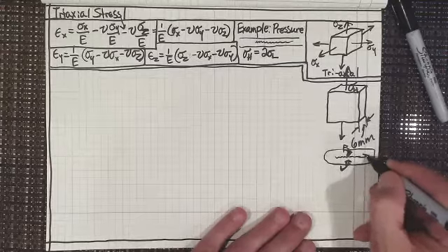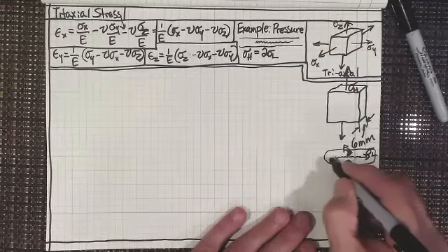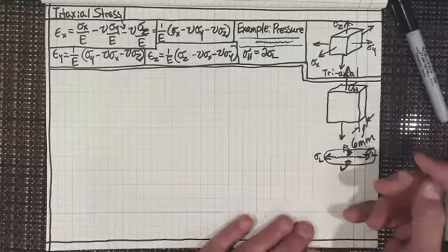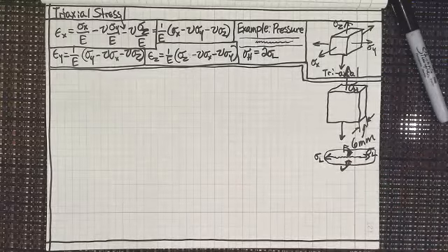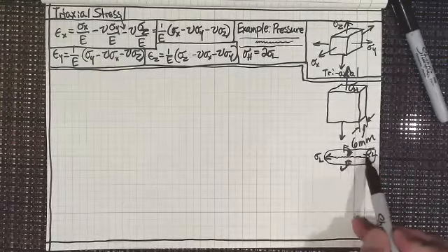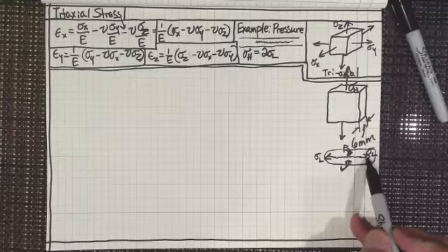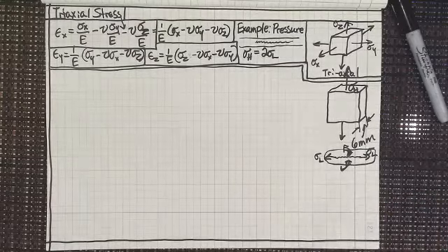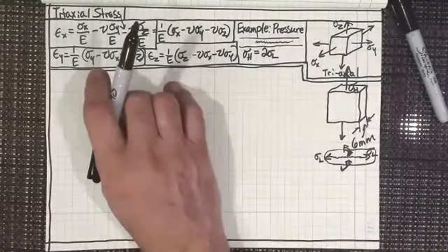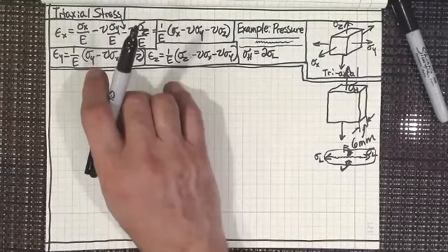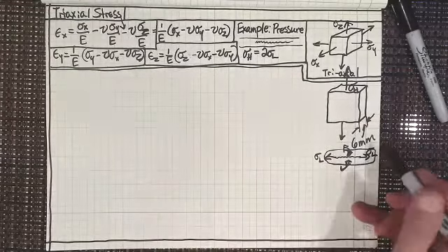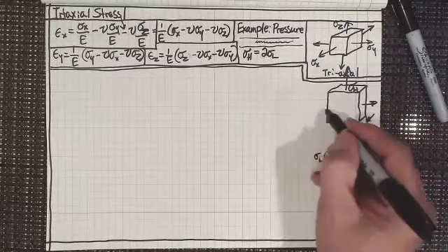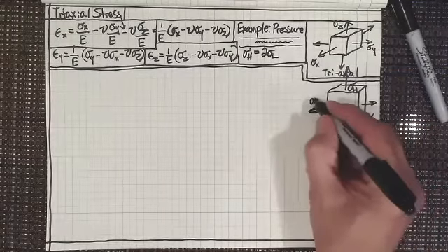And then the longitudinal stress is going this way. And that's always much smaller than the hoop stress. That's why the hoop stress always rips that big seam in the side of the pipe rather than ripping the pipe apart and blowing it up. No, if a pipe blows up, someone's put a stick of dynamite in that pipe. So then this is going to be my longitudinal stress.